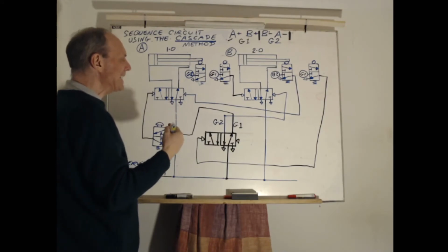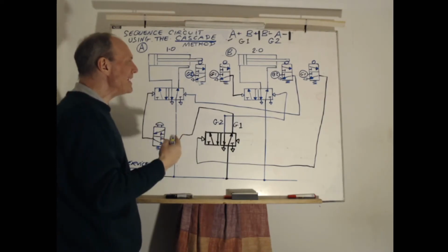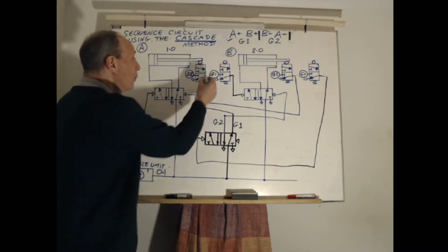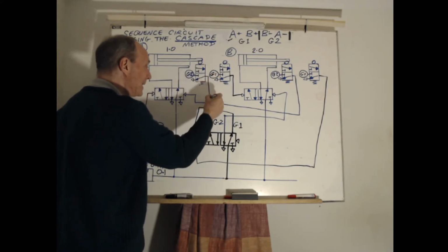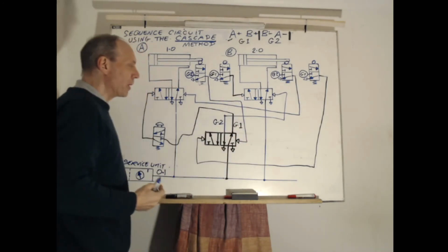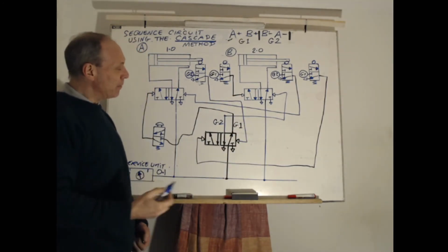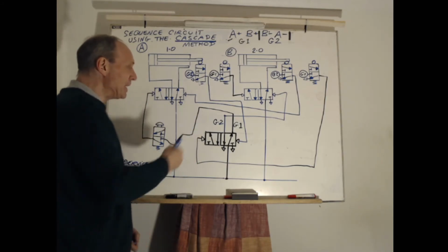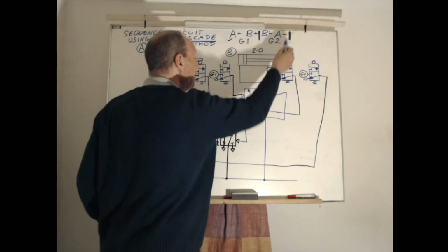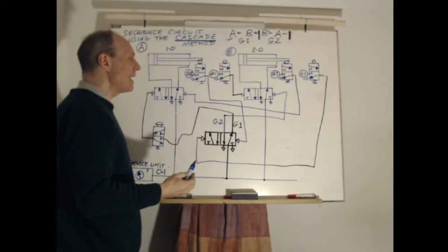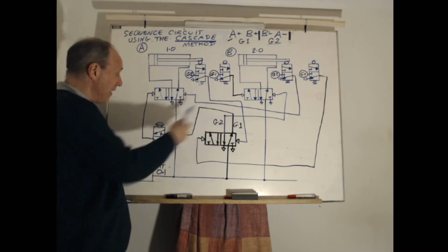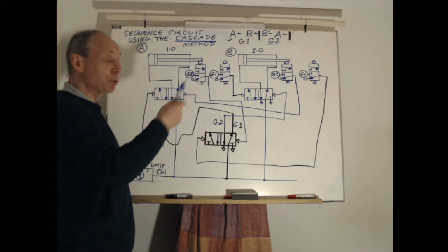So what it needs to do, it needs to eliminate G2 and bring on G1 again. So we can take this signal, which is the trap signal position, we can bring it down and we can swap the directional control valve back. And when we swap it back, G2 has been vented to atmosphere. The trap signal has been eliminated, plus the G2 supply, and we're now back online with G1. Of course, if the push button is pressed again, it will go through the sequence.